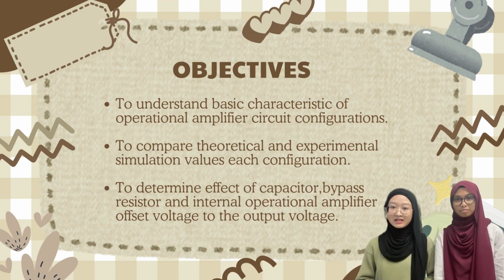The primary objective of this laboratory was to investigate five operational amplifier circuits. The first one is the inverting amplifier, then the non-inverting amplifier, integrator, differentiator, and summing amplifier, by using LTspice simulation. From this lab, we are able to understand the basic characteristics of these configurations, and also able to compare theoretical calculations with the experimental simulation values.